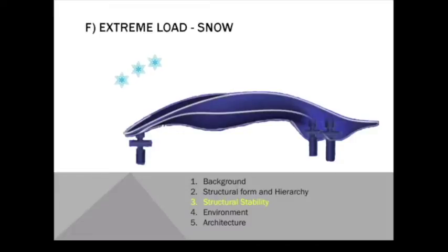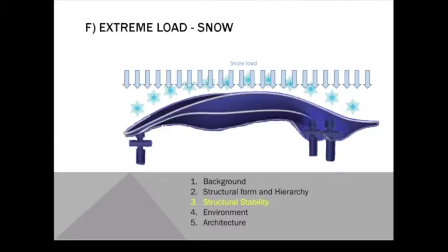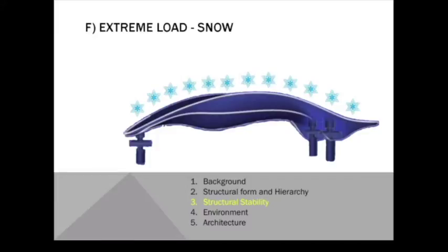Snow has two effects, one which is gravity load, and the other is the melted water effect. Thickness of accumulated snow can be used to measure the snow load. It depends on the snow and wind both. In this structure, both ends of the roof are lower than the middle, which can let the snow slide down. The second effect is ponding, which is water that results when snow melts. The gutters on the roof are designed to drain this water.